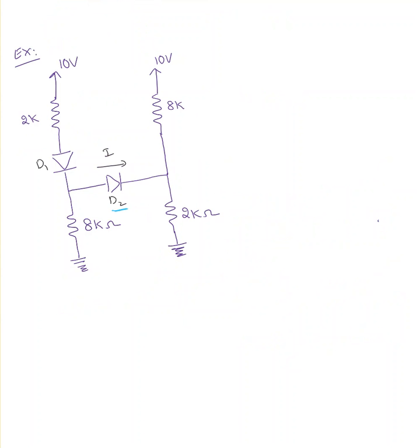Step 1, I'm not going to write it down: find all the outer node voltages. An outer node is nothing but a node which is going to the other elements of the circuit which are not shown in this figure. So this is going somewhere else. Something else is connected there, something else is connected there. We don't know what it is. All we know is the node voltage at that point and the node voltage here, and we know that this is grounded, so ground voltage is 0.